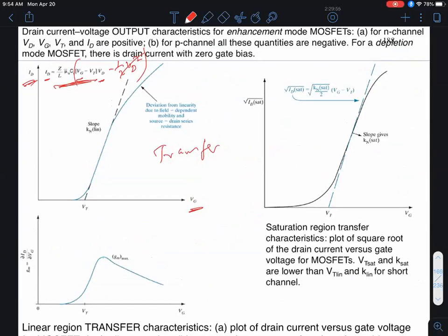Okay, so you see that if I plot output current as a function of input gate voltage, I should get a straight line whose slope would depend on this prefactor. Okay, and that's what I call K, or the gain of the device. Why is it called gain? It's called the gain because it's sort of change of an output characteristic, my output drain current, as a function of an input signal, the input gate voltage.